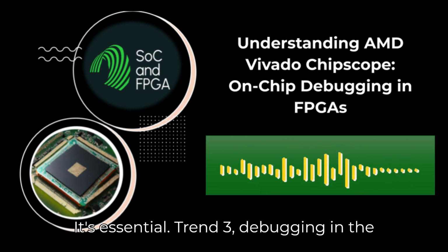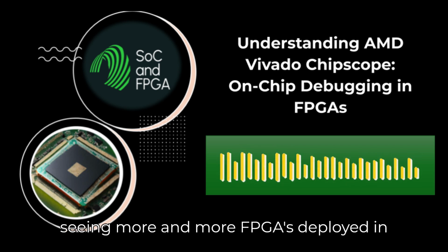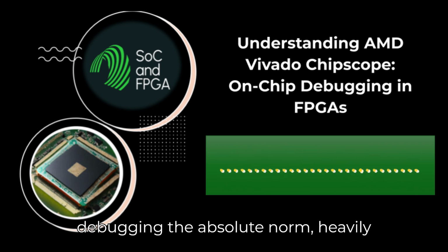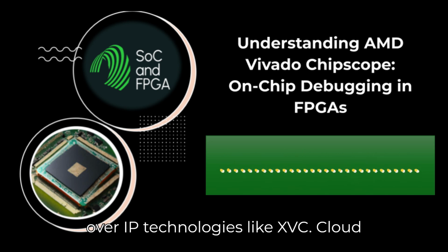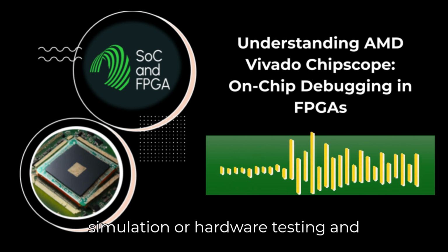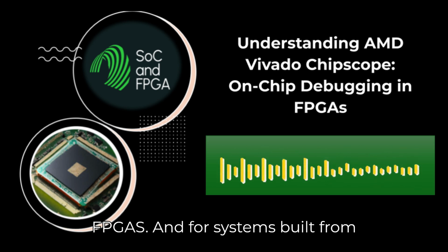It's essential. Trend 3, debugging in the cloud and distributed systems. We're seeing more and more FPGAs deployed in cloud data centers. This makes remote debugging the absolute norm, heavily relying on those virtual JTAG or AXI over IP technologies like XVC. Cloud infrastructure also enables new possibilities, like massive parallel simulation or hardware testing and automated fault injection campaigns running across hundreds or thousands of FPGAs.